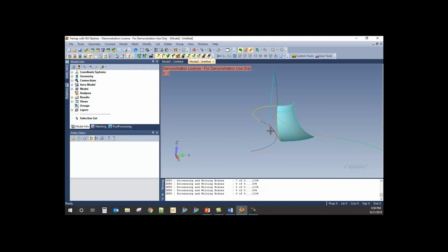And so let's say you are migrating or importing data from different sources. That's no problem, because as long as you change the tolerance on these solids, Femap can quickly infer that these two are meant to be together, for example.